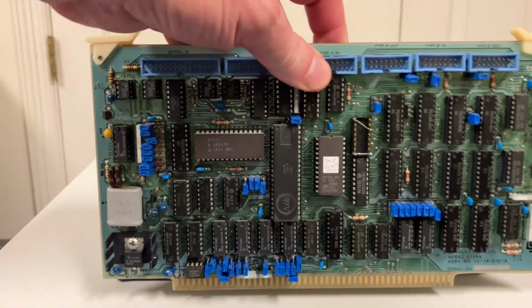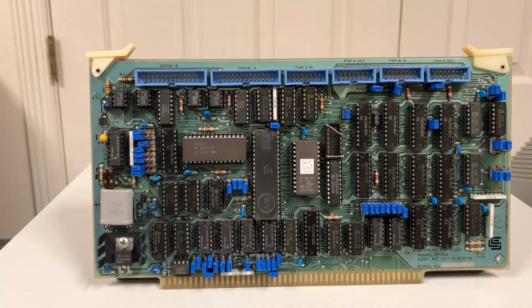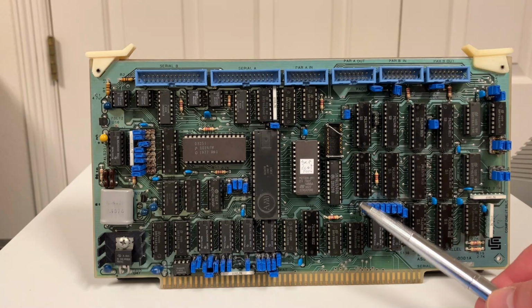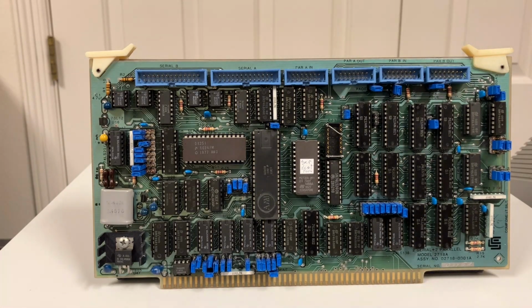So at that point, the serial board is ready to go to look just like a cassette interface. Now, as far as the EEPROM goes, we set the address with the first 5 of these jumpers. I have it set at F800. So this EEPROM will run from F800 through FFFF, the top of RAM, the top of memory space.